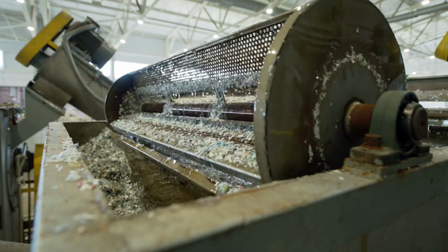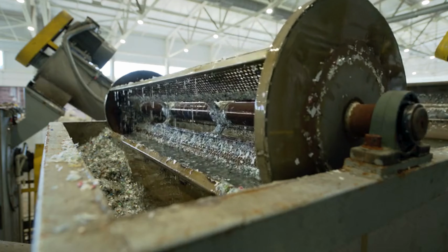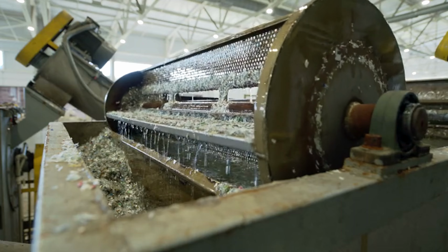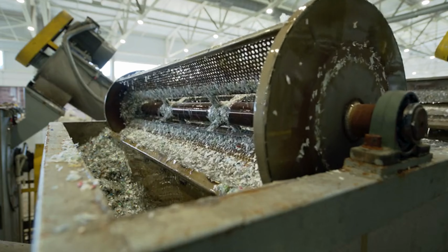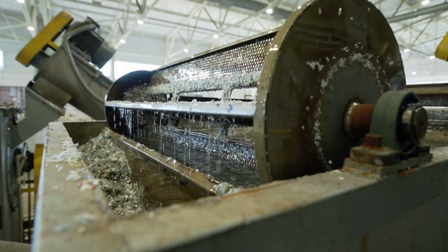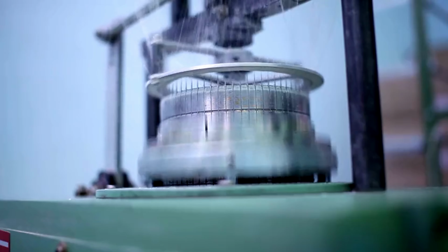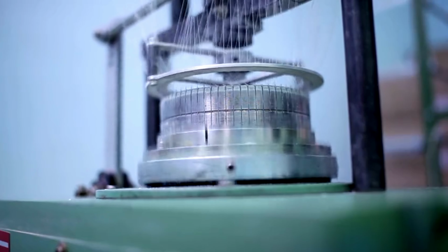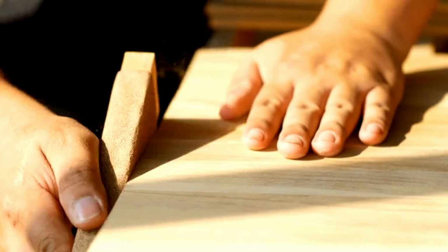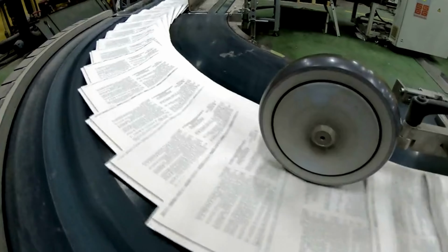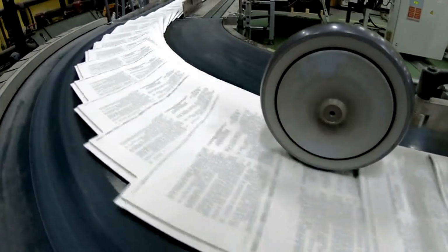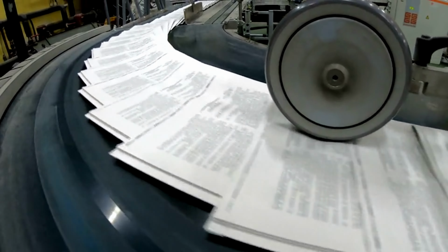2. Pulping. Separating fibers. The goal of pulping is to break down wood or recycled material into individual cellulose fibers, while removing unwanted components like lignin and resins. A. Mechanical pulping. High yield, low cost. Wood is ground or refined using mechanical forces. Produces weaker, more opaque paper, for example, newsprint, catalogs.